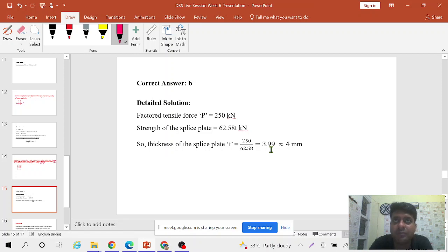But when code books are not allowed in the examination, you will not think that you are expected to round up those values. You can only think the examiner will ask you to be on the safer side, means 4 mm. They are not expecting that if 5 mm comes, then you have to give 6 mm. Like that, in case of weld, you check the minimum value of weld, whether my value is coming lesser than the minimum value of weld. In that case, you have to provide the minimum weld size. So like that.